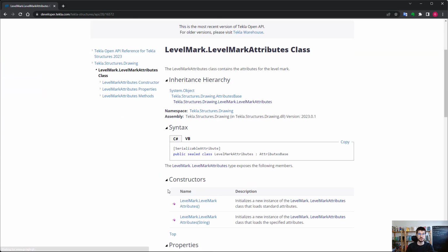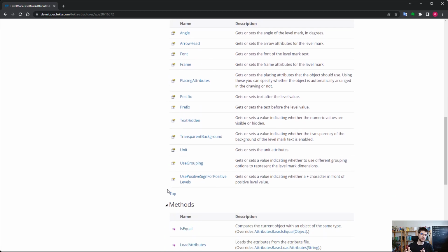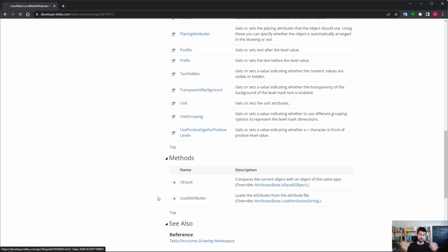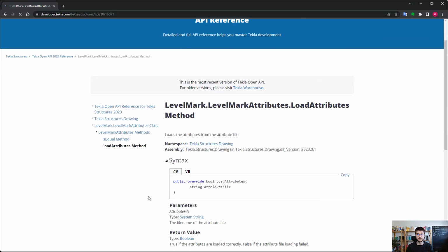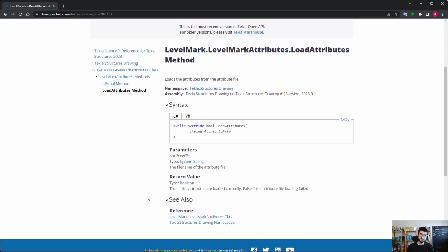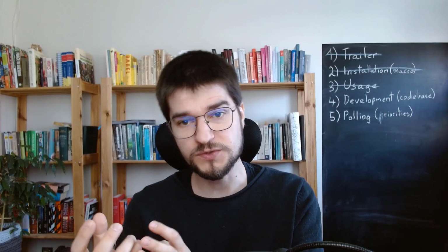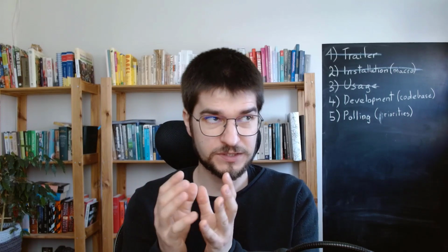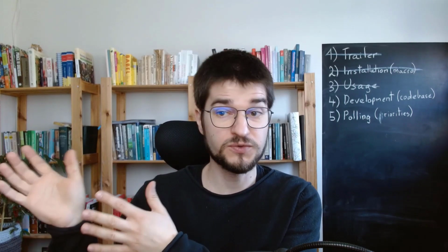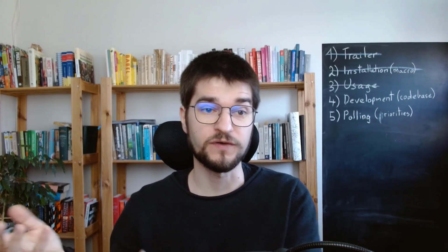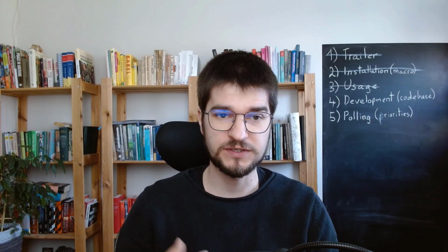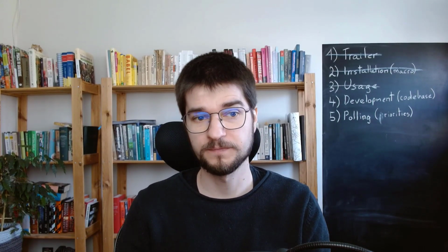Every Tekla drawing object has a lot of specific attributes, usually taken from a preset file from the environment or model directory. At this point of Tekla Drawing Link, I prefer to give the user the ability to specify a ready-to-consume attribute file. This shifts the workload to the user. She has to provide settings needed for the desirable look of the output.